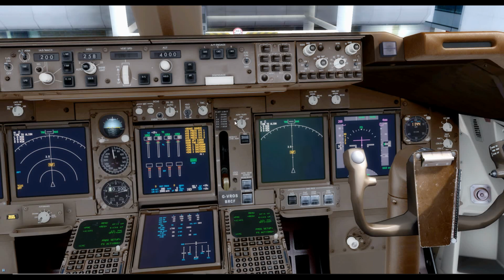Also looking at the alternate flap selector, we've already looked at that as part of the security check. We've already looked at this as part of the safety inspection, but needs to be off and no lights illuminated in the arm push button. No indications either in the alternate gear extension switches, and these are guarded.